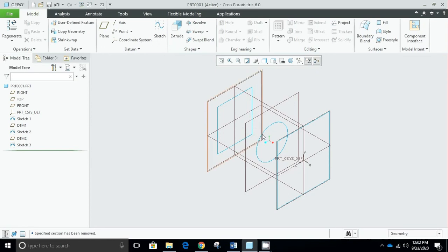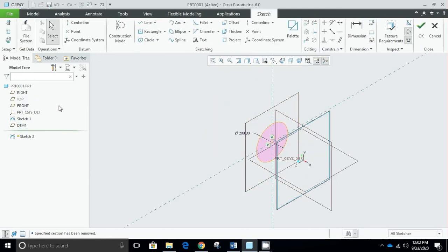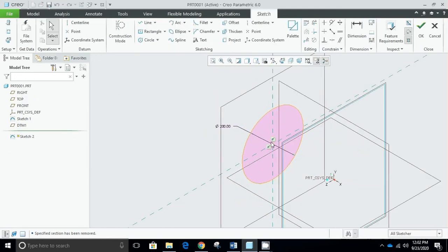And in sketch number 2, I have to edit this sketch and add vertices by using this divide tool. If I select it, and then over here my first division, so that the starting points coincide with those of the rectangles.